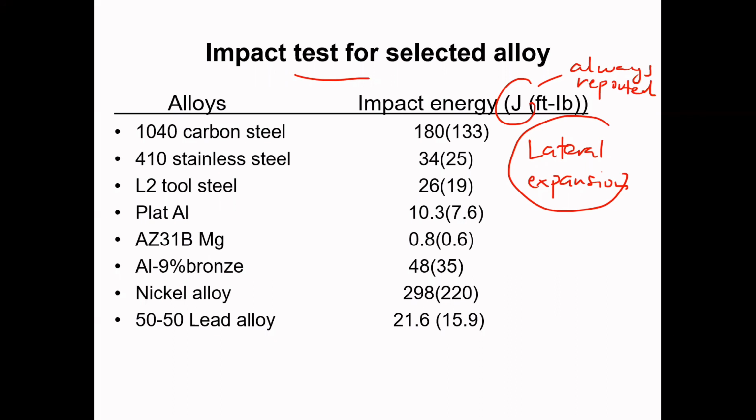It should be emphasized that Charpy tests are qualitative. The results can only be compared with each other or with a requirement in a specification. They can be used to calculate the fracture toughness of a weld or parent metal.